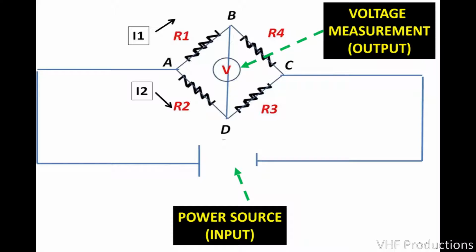If they have two choices to flow towards point C, the electrons can flow along path ABC, or the electrons can flow along path ADC. If the resistance of the two paths are identical, then there's no difference in the current flowing across the two paths, and therefore I measure no voltage across pins B and D. I will see no voltage output. However, if the resistance of either path changes, then there will be an output voltage that's measurable across pins B and D.